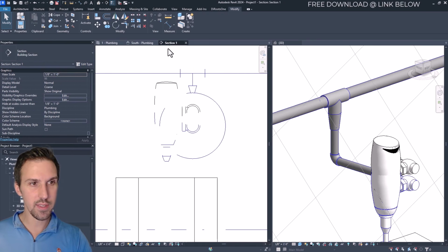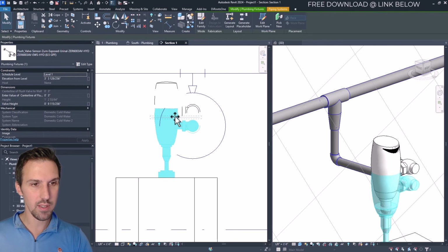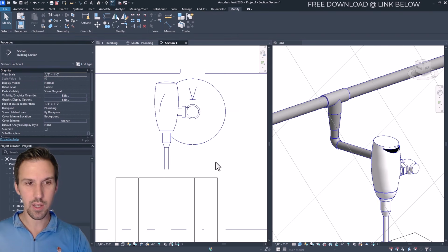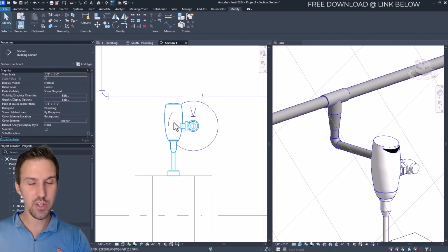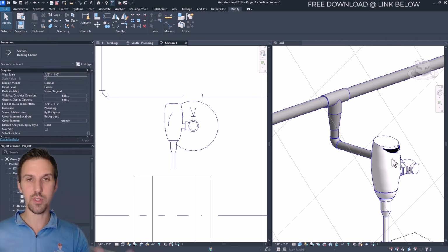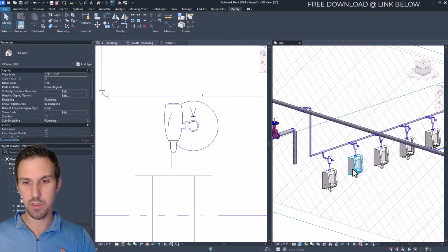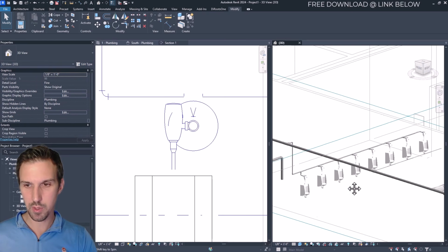Now let's go back to the section view and let's see if we can raise this thing back up. So I'm going to raise it up to here, and look, we were able to make that connection and raise it back up, because sometimes Revit just can't initially make the connection work, but when you connect it and then re-raise your stuff, sometimes you'll be able to make it work. So we were able to make that work by those techniques, and you're going to have to do that a lot in Revit. So that's good practice.